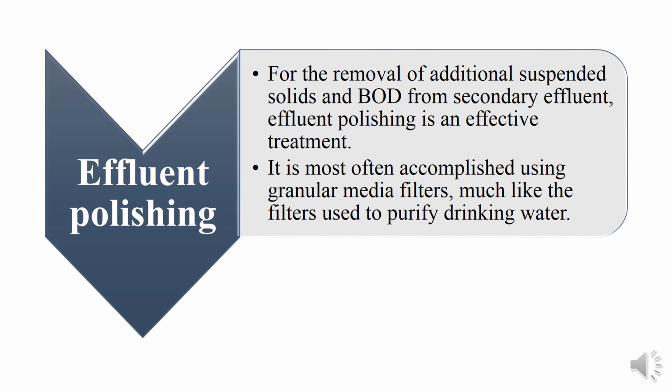Effluent polishing. For the removal of additional suspended solids and biological oxygen demand from secondary effluents, effluent polishing is an effective treatment. It is most often accomplished using granular media filters, much like the filter used to purify drinking water.